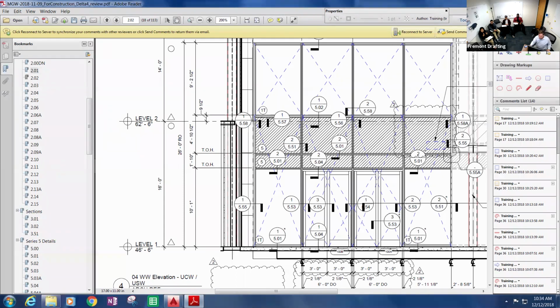Just to clarify, for doors, is that why usually around doors you need a little more stiffening, depending on the unit breakup? It's not necessarily because of the force of a door, it's just because of the way the unit is broken up, which causes more tributary area. So it's not necessarily force on the door. Initially I thought it's because there's some kind of door loads we have to account for, but it's not. No, not too much.